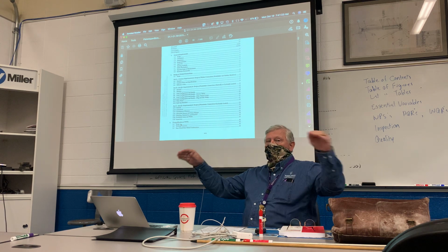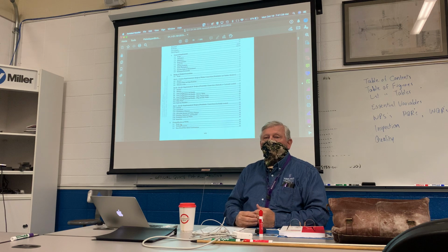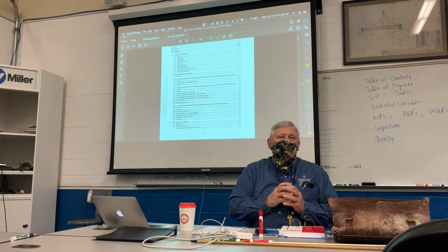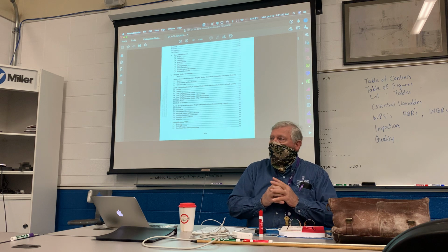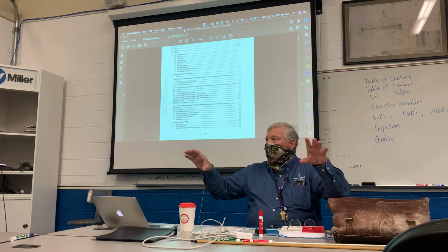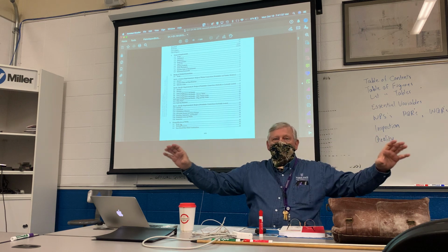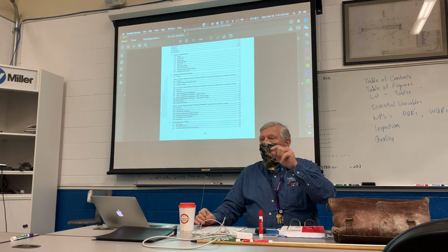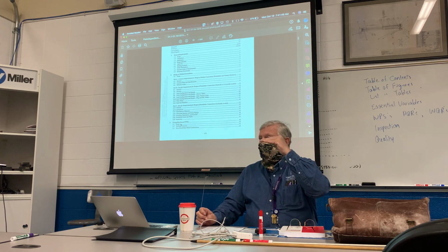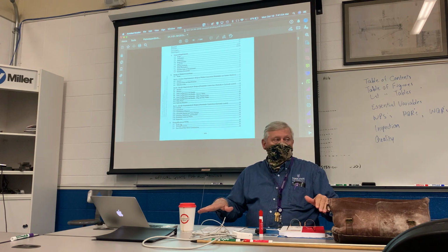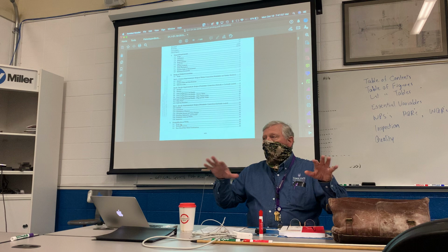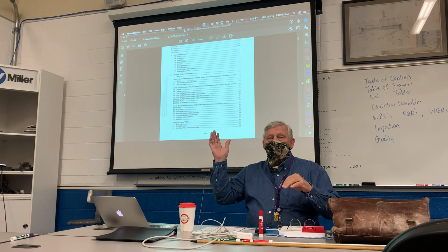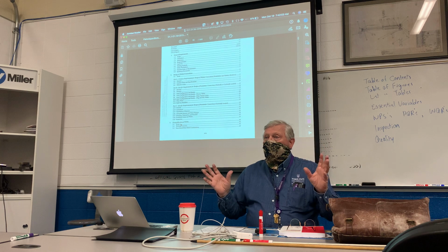If you're building bridges, and we've had a flurry in this country in the last 10 years of all these specialty bridge making, like for parks, they make these beautiful pre-cambered bridges that go across a brook or a stream, those guys have to make those bridges according to AWS D1.5. So there are all these different specifications for the D1 code that have subunits to it. D1.1 pretty much covers everything from 1/8 inch thick above to unlimited, and a lot of different kinds of steels.